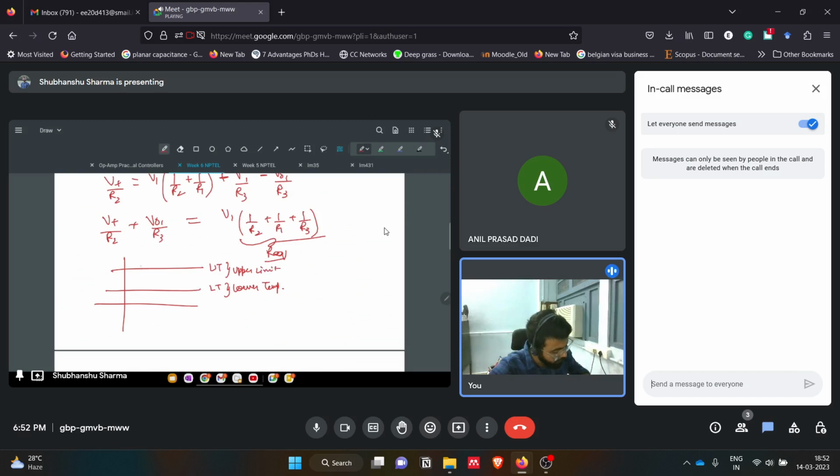So only when there is a transition. If the temperature is changing here, then nothing will happen. Once the input signal goes above this value or goes below this value, only our Schmitt trigger, or we can say the on-off controller, will give input to the heating plant circuit, and then some changes we can observe there.